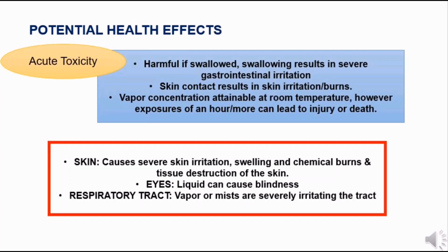Let's move on to the potential health effects of acrylic acid. Firstly, it is harmful if swallowed, and swallowing results in severe gastrointestinal irritation. If it contacts the skin, it will result in skin irritation or burns. The vapor concentration of acrylic acid is attainable at room temperature, and exposure of an hour or more can lead to injury or death.